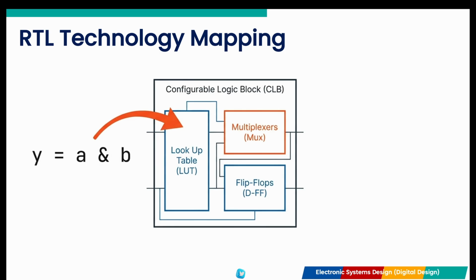Once optimized, the abstract mathematical operations must become real hardware through technology mapping. During this step, the synthesis tool takes your abstract logic, like ANDs, ORs, or additions, and maps them directly to the physical primitives available on the FPGA fabric.